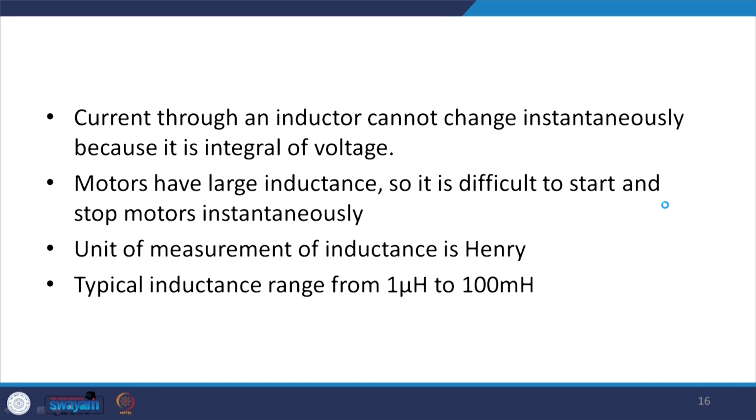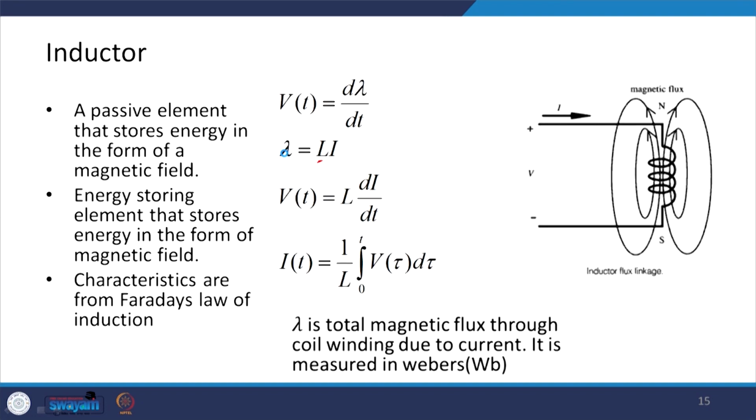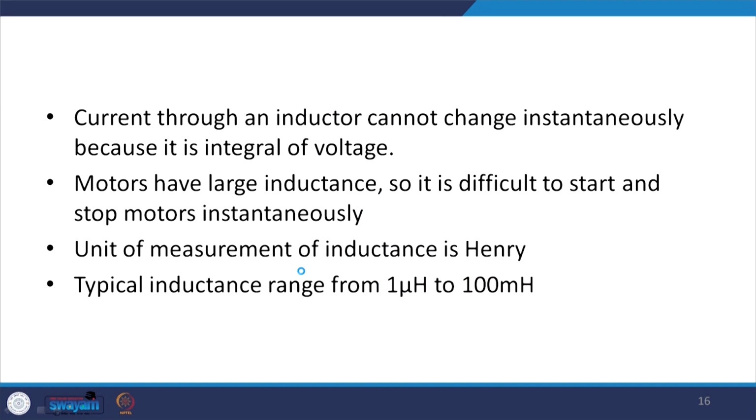So, the current through an inductor cannot change instantaneously because it is the integral of the voltage. Okay. So, here you can see that this current is the integral of the voltage. So, this cannot be changed instantaneously, and because of this we have something to look for in components which have high values of inductance and which are used in mechatronic systems. Motor is one of such components.